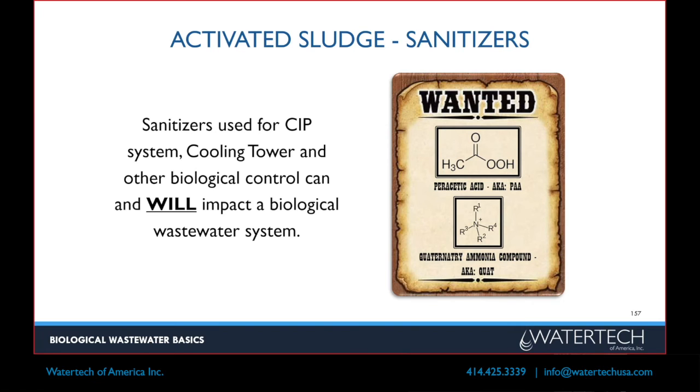acid. And then again, if those carry through into your effluent, then permits have limits for phosphorus and BOD and temperature and all that, but then facilities have to run toxicity tests, WET tests, on a regular basis. And these types of compounds, if they're present, will cause you to fail a toxicity test.